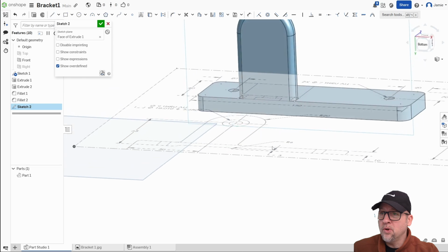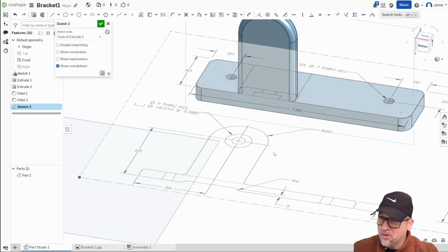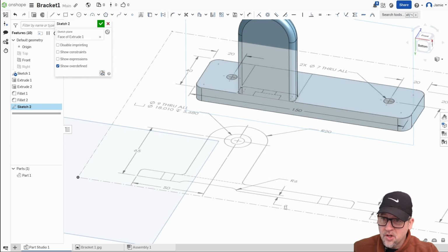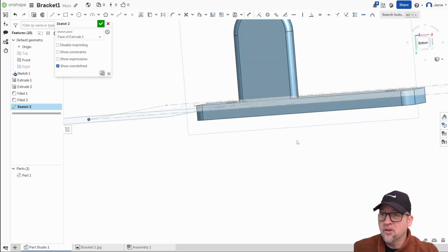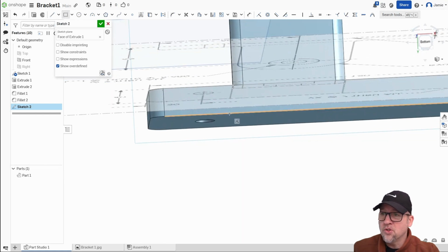So let's rotate using the right mouse button, pushing down, holding, and it rotates. We will go 3 millimeters, and then we'll have a 6 millimeter radius. First, we'll just make a block inside of there. So a 3 millimeter block aligned with this edge. So that edge right there, I think that should be good to go. So let's build a box, and we just choose wherever we want to go. We don't have to be perfect yet.